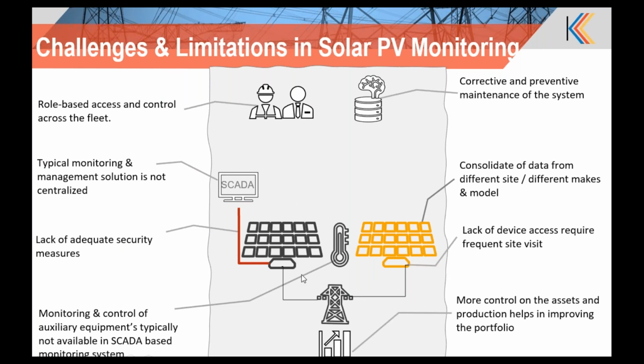And a typical system would be made for communicating with a set of devices, like a set of inverters or a set of controllers or PLCs in the field. You cannot make it a generic head end or generic data collection system for all types of inverters or all types of devices deployed in the field. So that is again one of the other challenges we are seeing in the legacy monitoring system. And the SCADA also does not provide secured remote access to these devices.